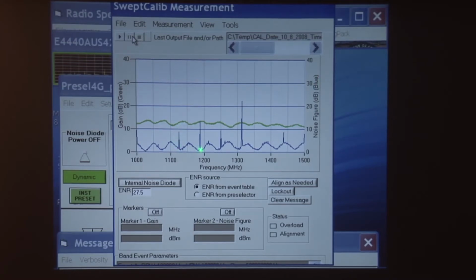Yeah, these spikes, as you said, Randy, are basically not good data points, but if we're taking a measurement, we can be aware of that, we can note these, and there are a variety of ways of working around that. These are due to some strong ambient signals that are coupling into the measurement system. But that's the basic approach if you're doing it with a computer-controlled system.